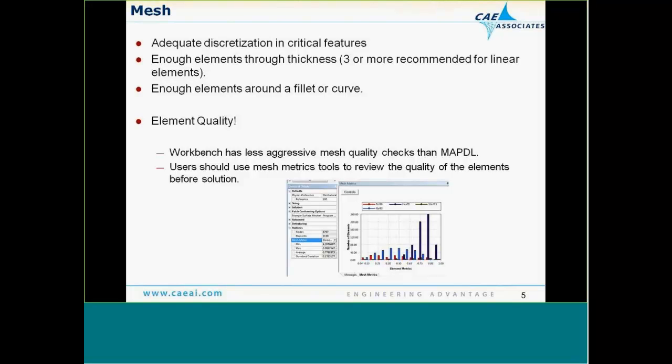When you use Workbench, it generates a mesh. It has less aggressive mesh quality checks than MAPDL has, for those of you who used to use classic ANSYS. But Workbench offers a mesh metrics tool that will let you review all of the quality measures before doing a solution. If you've noticed when you've used Workbench, it never generates warning elements.